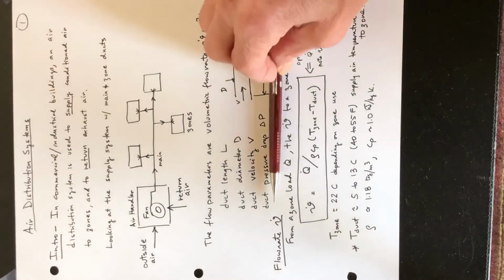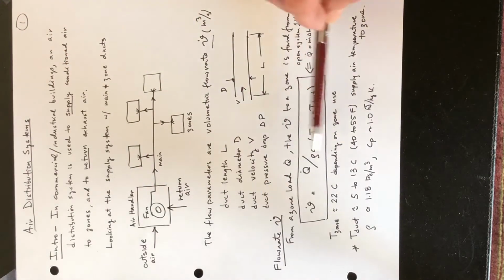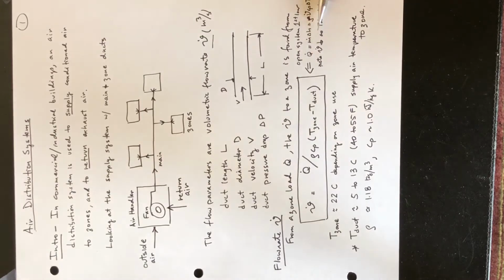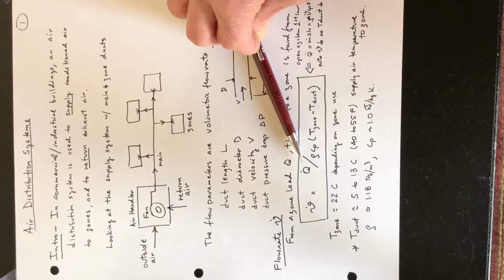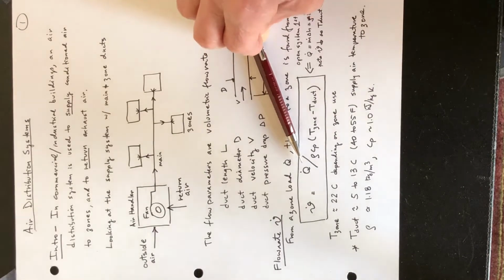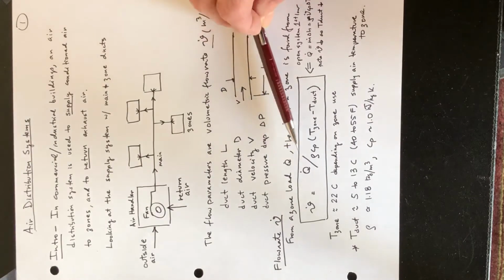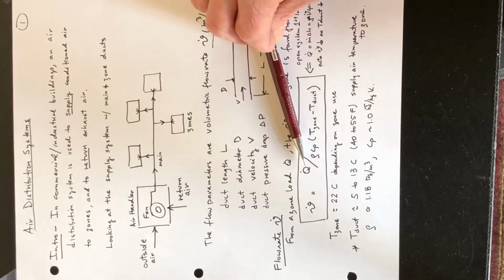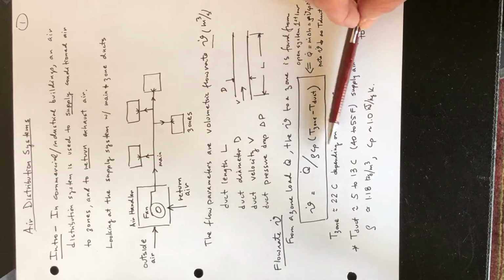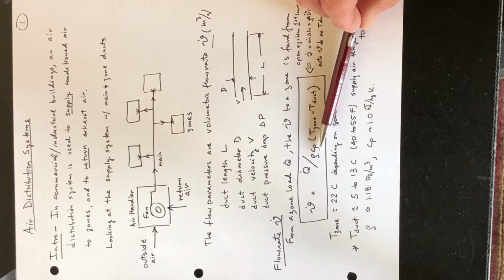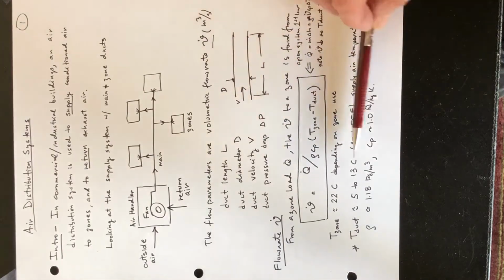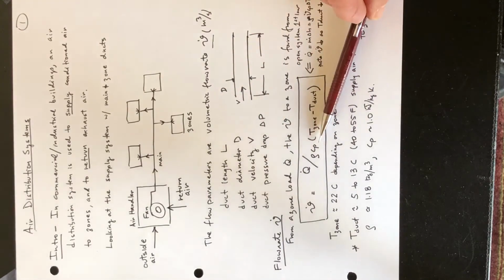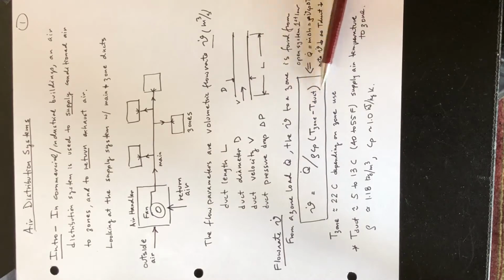How do we know the flow rate to a zone? Well, that's basically given from the open system first law. If we know what the zone load is, that again is a function of the number of people, what they're doing, equipment, and also environmental conditions such as sunshine that create the given zone load. And then the first law indicates that into the zone load we factor in the density, specific heat of air, and then the temperature difference.